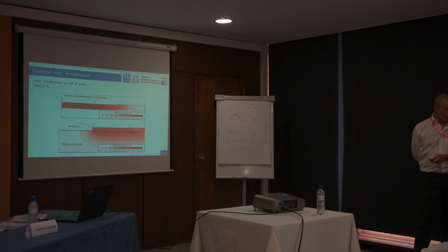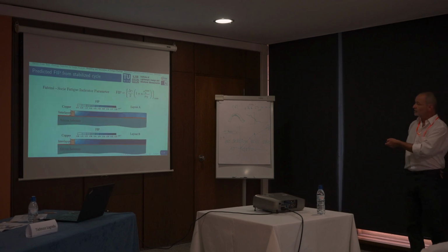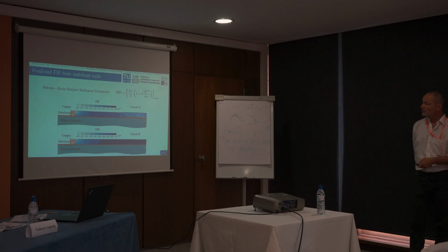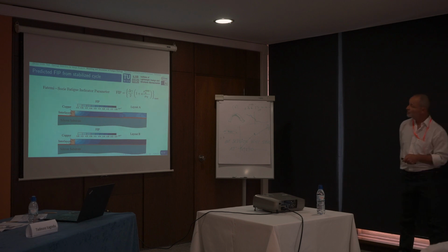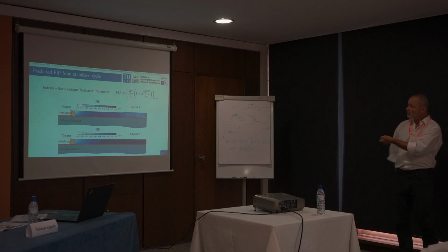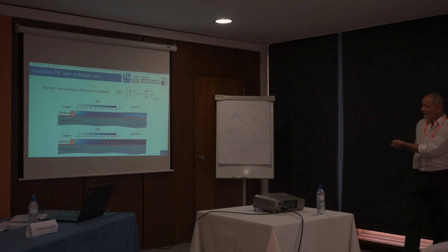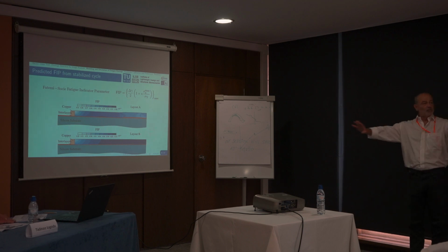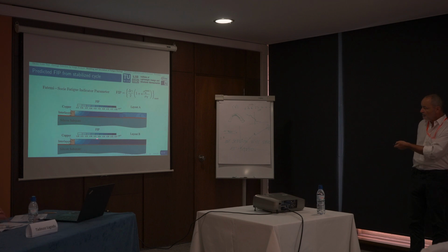the elastoplastic modeling. And with this, again, with the Fatemi-Socie fatigue indicator, the most important influence is the shear strain range and the critical plane approach. So if we look here on top, we have design A. We see that we have some gradient in the fatigue indicator, but it's not very strong. So along the surface here, that's quite evenly distributed, at least in this region. In design B, it's even more uniform. Yeah, that's design B.